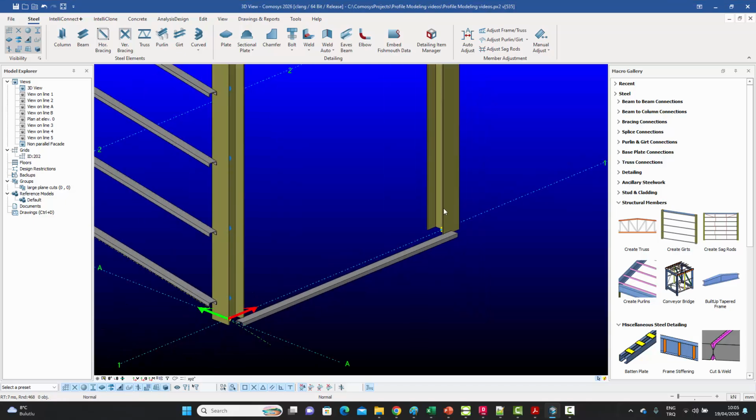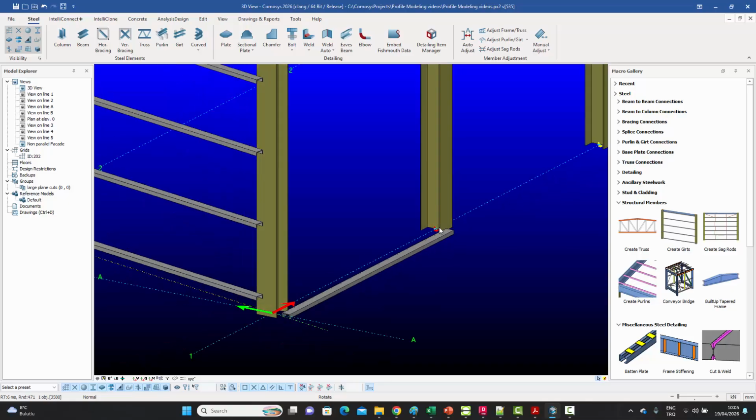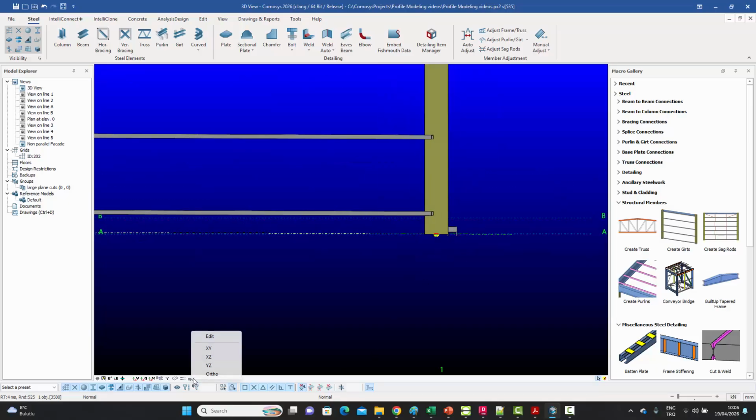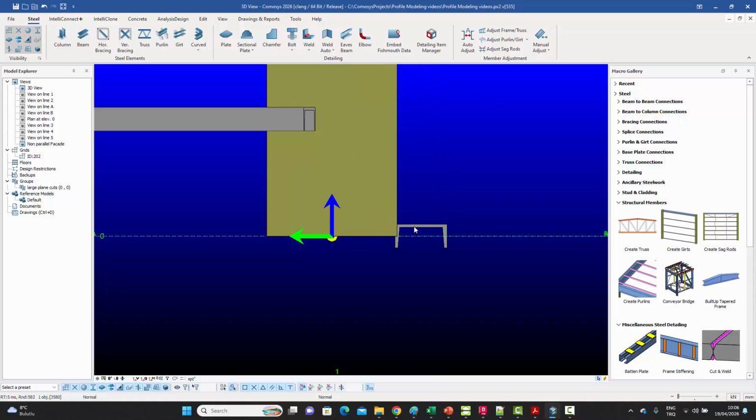So I'm still connected to the column as far as the finite element thing is concerned, and now I'm at the correct position as well as far as the offsets are concerned. I can look at it from like that and see that I'm in the correct position. Of course, one more thing I need to do is this. I'm sorry. Control W like that.